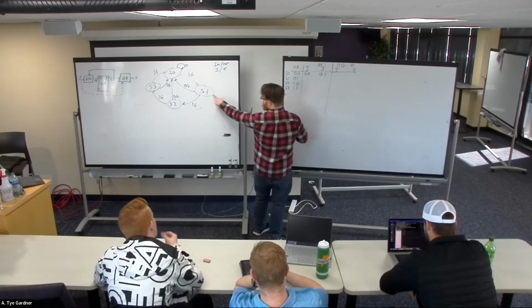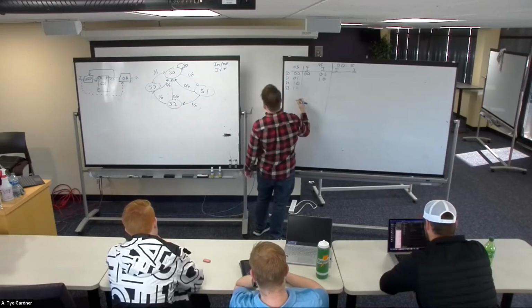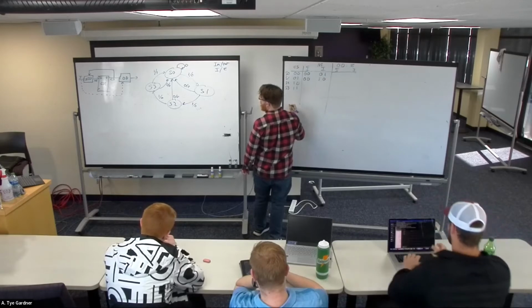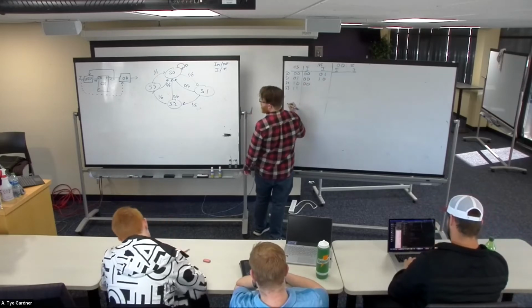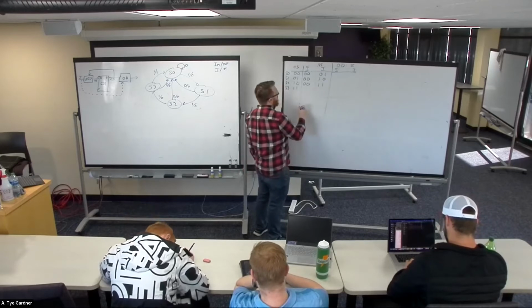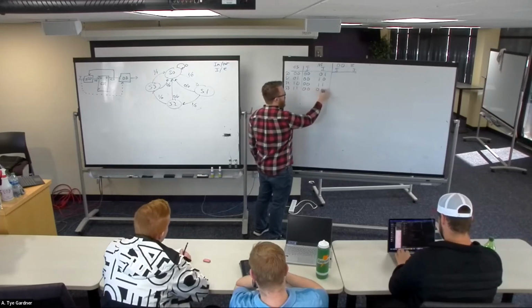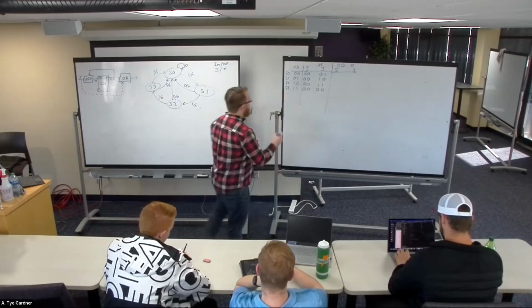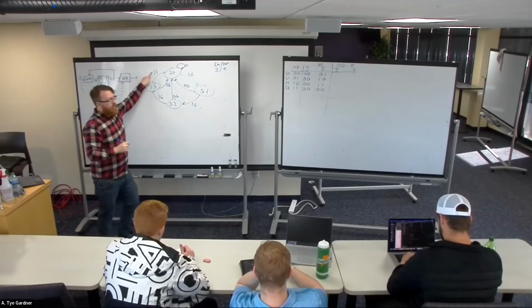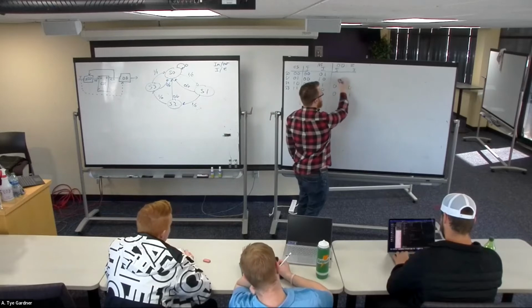If I look at state 1, then if I get a 1, I go to state 2. So that's 1, 0. And if I get a 0, I go back to 0. If I get a 0 in state 2, I go back to 0. And if I get a 1, then I go to state 3. Then if I'm in state 3, whether I get a 1 or a 0 doesn't matter, I'm going to state 0. The only situation in which my output is 1 is if I'm in state 3 and I see a 1. So I come over here and say I'm in state 3, I get a 1, this is a 1, everything else is 0.